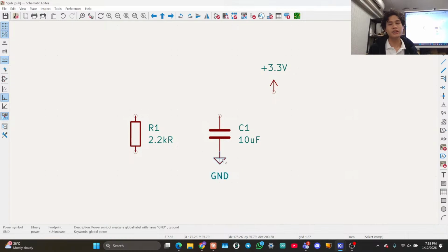Okay? Okay, so you can see that I placed my ground directly on top of the circle of this capacitor. So this capacitor, the circle basically means that it's a connection point. You can do things to that circle. Okay? So if I connected ground here, it doesn't do anything. Alright? But if I put it here or here onto a circle, then it makes sense.